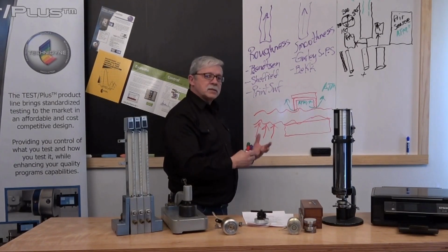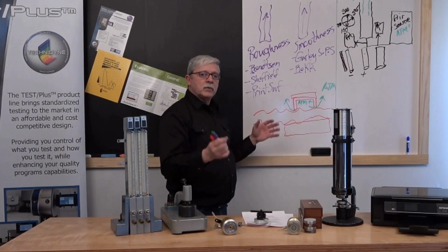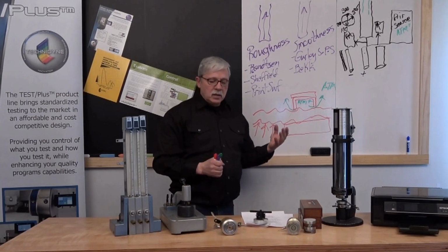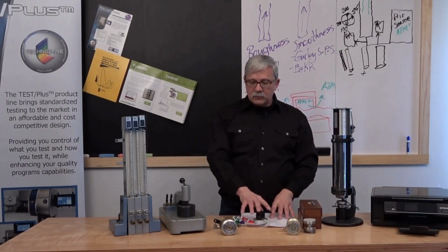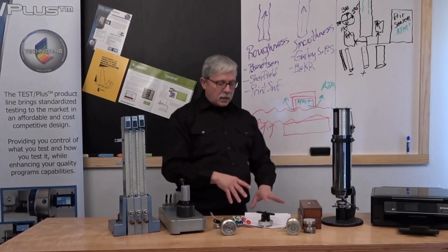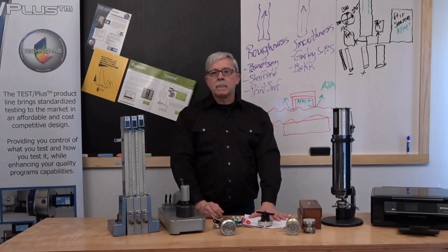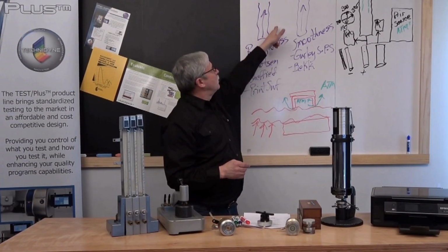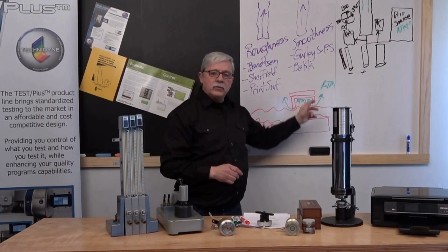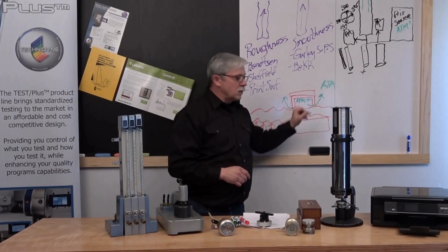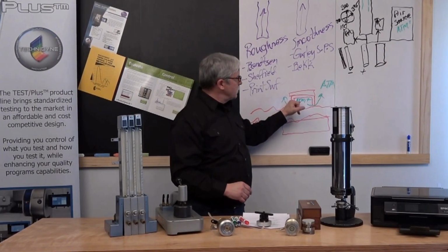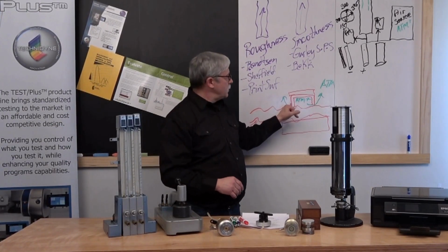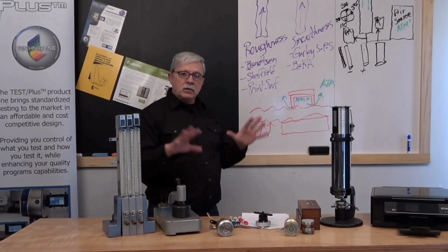So we create this pressure drop. We measure the air that's flowing out from underneath these measuring lands, or this pocket, and we can assess, in a relative sense, what kind of surface topography we have with the product that just came off our paper machine. If that surface is rough, obviously we're going to get a high flow of escaping air out from underneath these two annular rings. If that surface is relatively smooth, we're going to increase the restriction because we no longer have a lot of passageways underneath these metering lands for the air to escape.